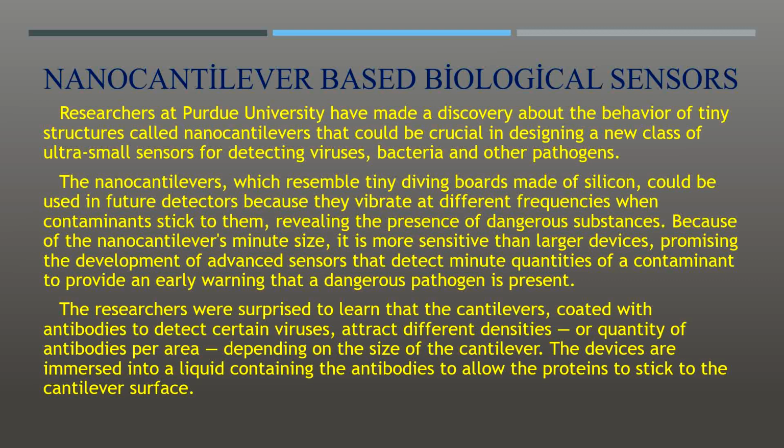The nano-cantilevers, which resemble tiny diving boards made of silicon, could be used in future detectors because they vibrate at different frequencies when contaminants stick to them, revealing the presence of dangerous substances. Because of the nano-cantilever's minute size, it is more sensitive than larger devices, promising the development of advanced sensors that detect minute quantities of a contaminant to provide an early warning that a dangerous pathogen is present.